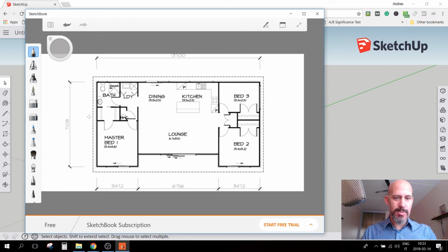So what I see immediately is that there is no way you can build this particular house with a prefab system. And the reason is that the external walls are too thin. You see, this is like what? I have no idea, but it's like less than 20 centimeters. Now, if you're building a house with timber frame elements, the thickness of the wall is gonna be in the order of 30 centimeters. So I would say 337 millimeters is the right size.